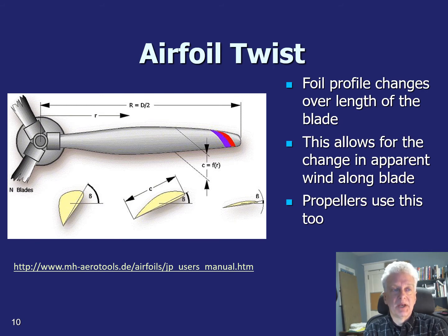In the middle of the blade, it's a medium thickness and a moderate angle of attack with a long chord. And out at the tip, because it tapers, the chord gets a little shorter, the angle of attack is very small, and that all optimizes so that each part of the blade is producing angular moment in concert so that they all contribute equally to the torque.